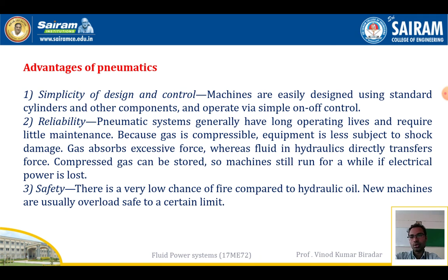Maintenance is also not much compared to a hydraulic system. Next one is safety. By using this pneumatic system, the operator has safety. There is a very low chance of fire compared to the hydraulic system. Not much fire takes place in a pneumatic system as compared to a hydraulic system. This is one of the most important advantages of using this pneumatic system.